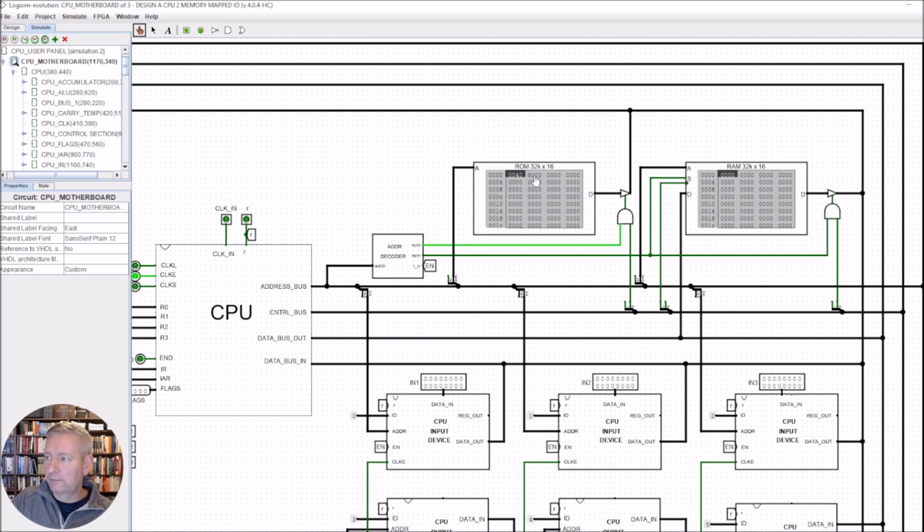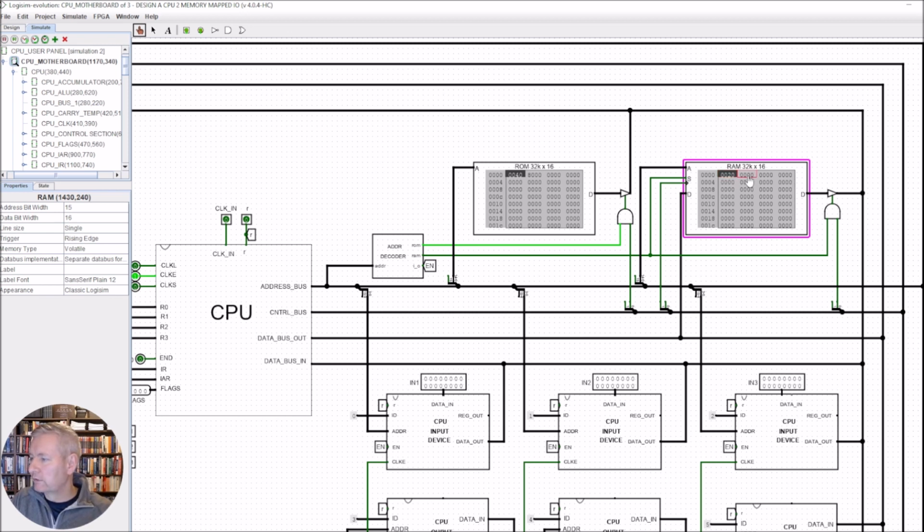Now, where's it going to find that address? It's going to find that address in the RAM, because that's the start of the RAM. So you could put a program in the RAM. For example, 0020, which is just a data command, and you could put in, say, 000F, and then we could finish it off with 00CF. All this does is take the value 000F and put it into one of the registers.